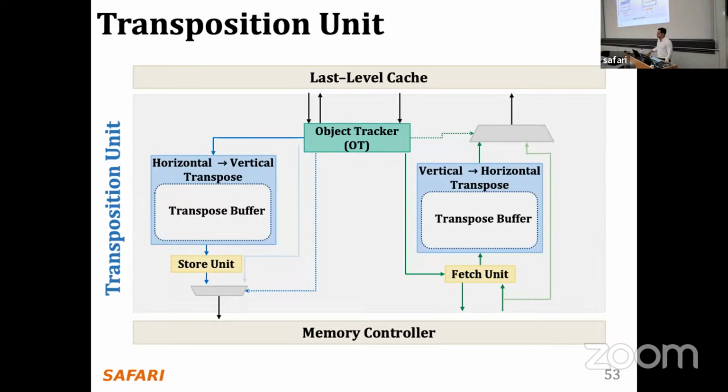At initialization, you would have to write data to the DRAM, assuming the new data layout. When you're just initializing, the data is going to be written in the traditional horizontal data layout. The moment that the data starts leaving the cache, the data is going to start being transposed, because you don't initialize data inside the DRAM, right? So we initialize data in the cache, in the CPU, first, and then eventually it starts being evicted to the DRAM chip.